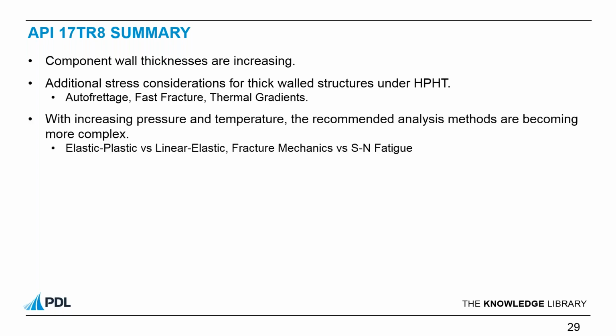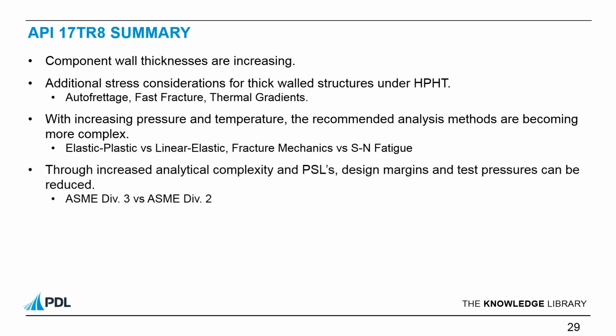So with increasing pressure and temperature, the recommended analysis methods are becoming more complex. So we're moving away from the linear elastic approach to an elastic plastic approach. We're moving away from SN fatigue and towards fracture mechanics based approaches. So through increased analytical complexity and higher product specification levels, the design margins and test pressures can be reduced, which is what we just looked at with ASME VIII Division 3 versus ASME VIII Division 2.